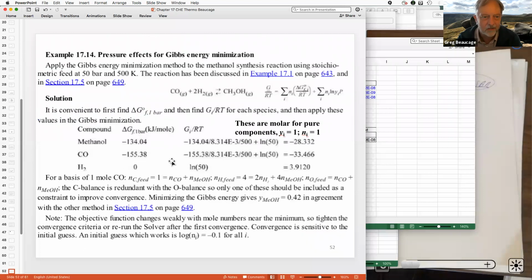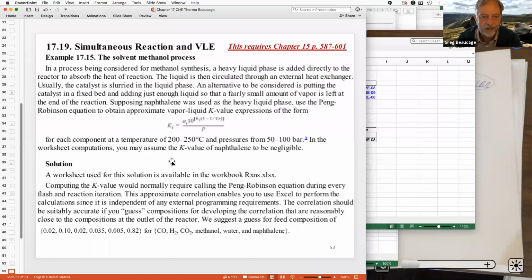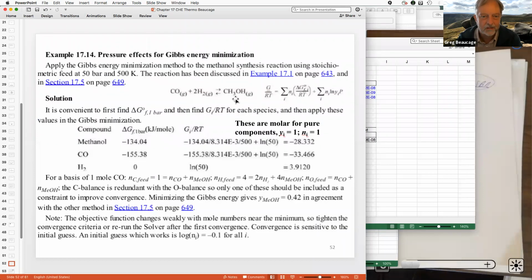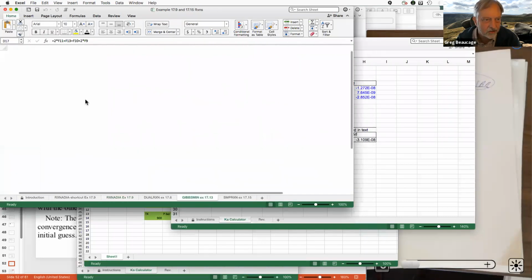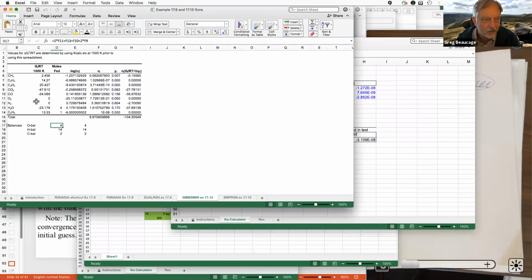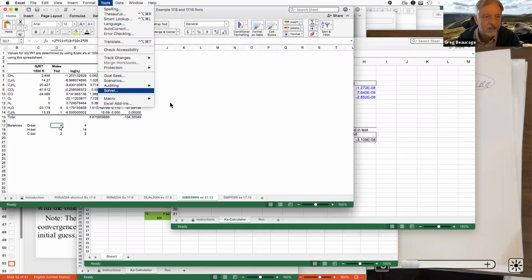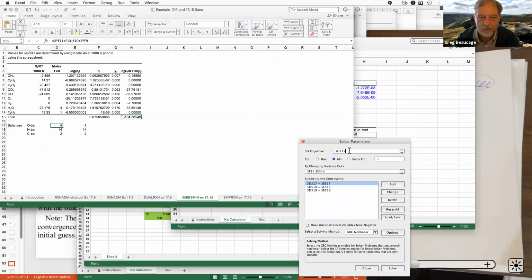Right, so he shows that for this methanol, or the same reaction, right? And that's in a spreadsheet back here. So this is something called Gibbs minimization. There's a huge number of reactants on this. This is like all those things. These are Gibbs formation. Then to find this, you minimize it. So the solver routine is just find the minimum in the sum of the Gibbs. Find the minimum in that number. Right. So somewhat straightforward given how complicated the thing is.